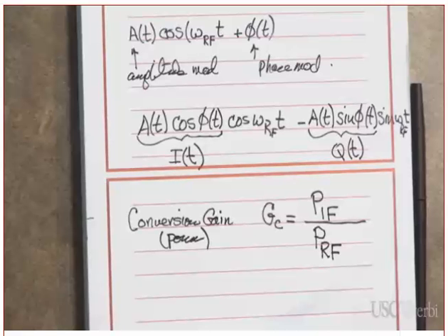They are not necessarily going to give you the same answer. Why? It will, because you are comparing an input to an output. You need to understand, is the input resistance the same as the output resistance? Are you following me or not? You need to look at what is the loading at the input. You are measuring the power on the input resistance, and the output power on the output resistance. Clear? So be careful when you see this one here.